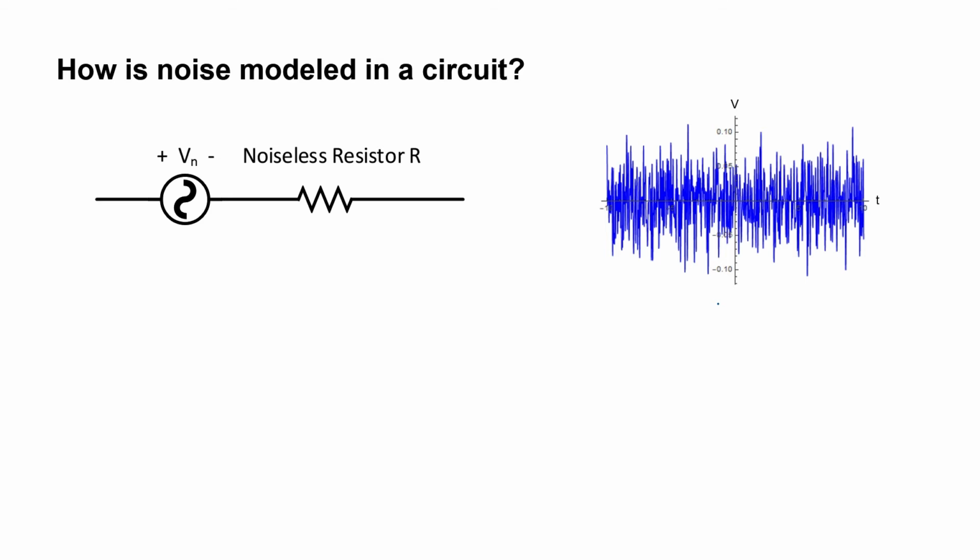So we have a source of power and we have a way to dissipate that power. And at thermodynamic equilibrium, of course, these two have to be the same. If I were to take this circuit fragment and hook it up to an oscilloscope and measure the voltage across the two sides of the circuit, I would get some plot like what we're seeing here on the right, voltage versus time. The average voltage due to the noise is 0. However, because this is something like an AC signal, we are going to have an RMS voltage. That RMS voltage, in a sense, represents the amount of power that's circulating around inside the circuit fragment.